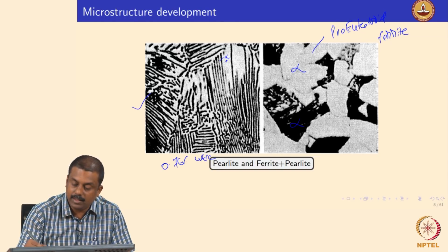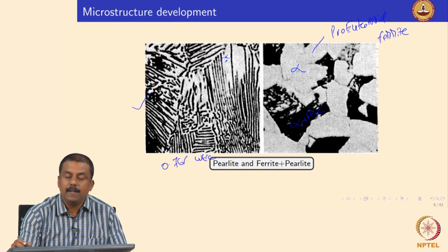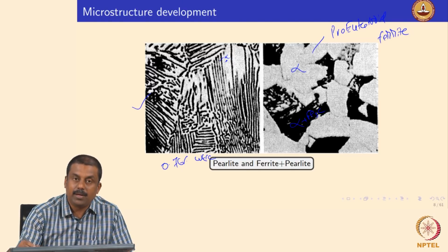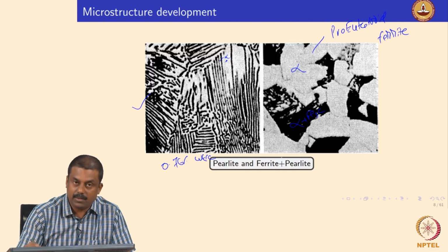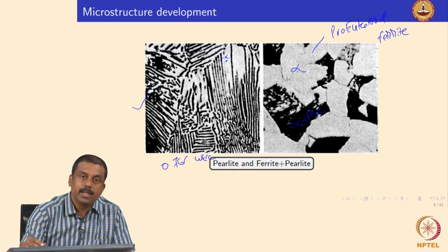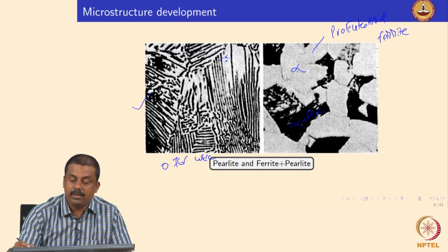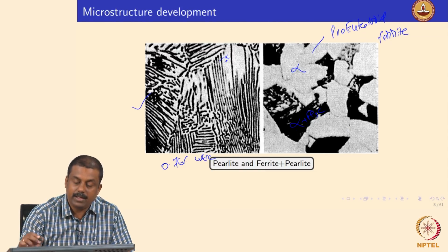So, this is eutectoid pearlite. Okay. So, a condition for this is your carbon concentration must be less than the eutectoid composition, which is 0.76, and most of our advanced steels' compositions would lie in this composition range, where if you are cooling sufficiently slow, you would end up forming ferrite plus pearlite, which is nothing but a mixture of ferrite and cementite.